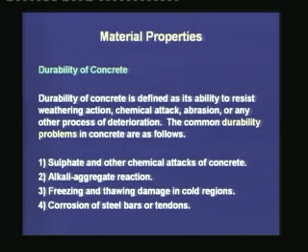In prestressed concrete, as compared to reinforced concrete, the amount of steel required is much less. Now, if the steel undergoes corrosion, then the problem in prestressed concrete is even more than reinforced concrete. The reduction in diameter of a prestressing tendon is much higher in percentage compared to the reduction in diameter in reinforced concrete reinforcement.